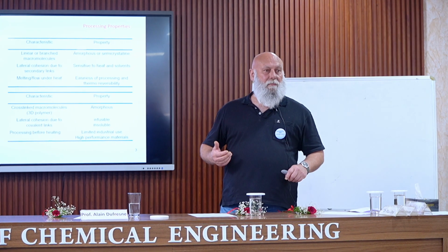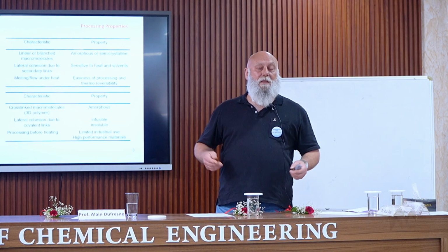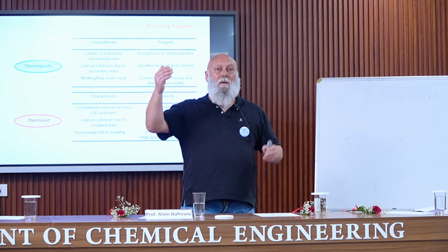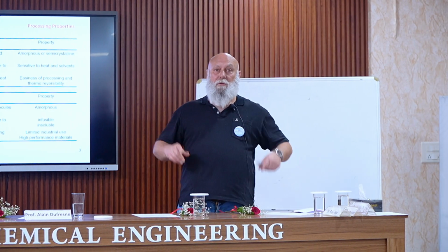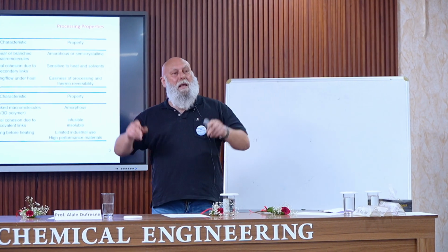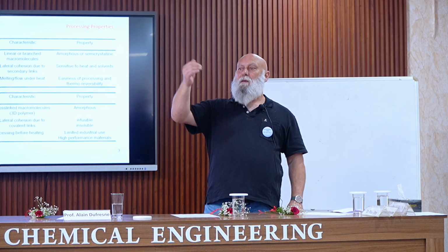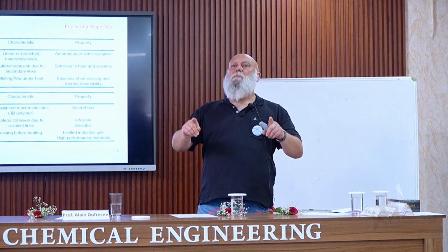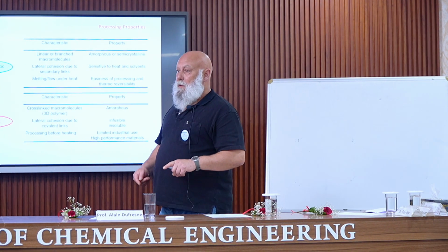Cellulose. Can you melt cellulose? No. When you increase the temperature, we have some strong hydrogen bonds between the macromolecules, meaning that it's a thermoplastic, but the secondary links are very strong. It's a highly cohesive material. And when heating cellulose, instead of separating the macromolecules, the polymer can be degraded, meaning that some covalent bonds are cut. Meaning that in this case, these secondary links are stronger than covalent bonds.